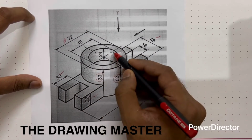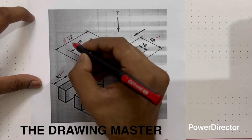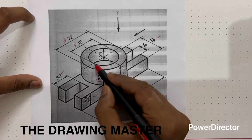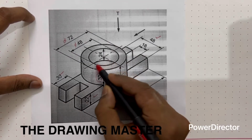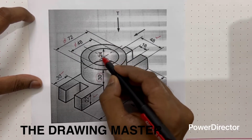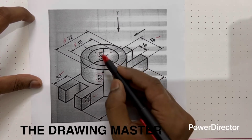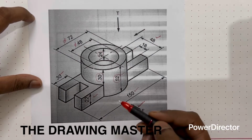Now this 72 is the dia of the cylinder. 48 is the dia of this hole. And depth of the hole is 24. Here you can see this edge and here it is given 24, means depth of the hole is 24. This is hollow till 24 mm only.